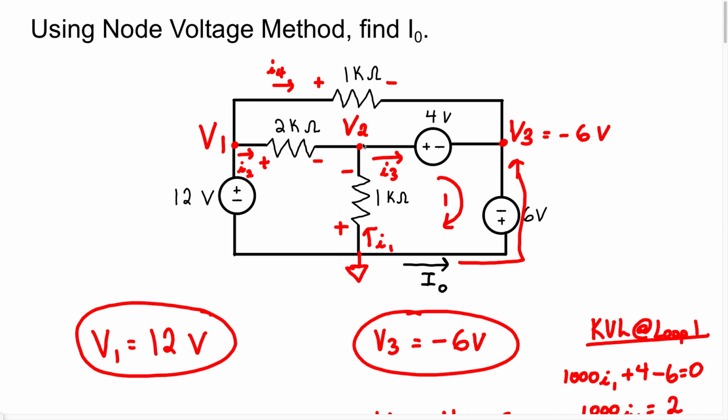But then you have to ask yourself, could we use KVL here? Could we use KCL here? Could we use series parallel resistance here? Because I asked myself those questions, I was able to know we have to use KCL, because they wanted us to find the current, and the only way to find the current in this source right here without a resistor is to use KCL at a node.